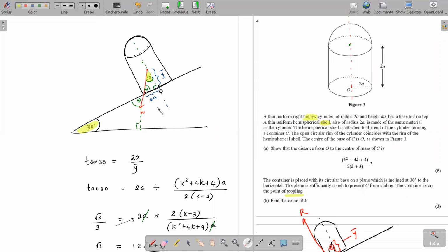That's the geometry you need to consider here, right? I've explained the reasoning behind this geometry in the theory work, so we are going to directly use this and build up our equation. This is your center of mass. The weight starts from the center of mass, from G, and from O to G is your y bar, because y bar is what we found in part A, the vertical distance from O to the center of mass.